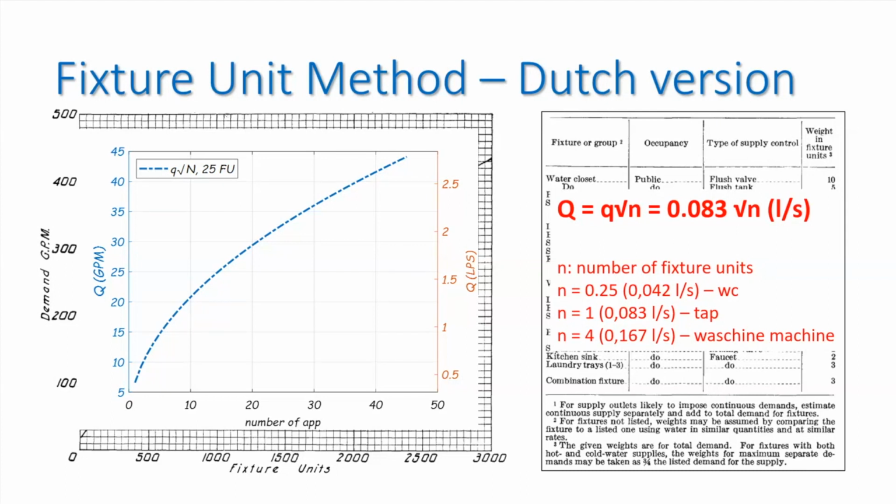And then the maximum flow from that is that Q square root N, which would account for the chances of simultaneous use. And the same would go, and that was where we probably went horribly wrong, or we believe, because we didn't have anything else, let's not just use it inside the apartment, but also outside.